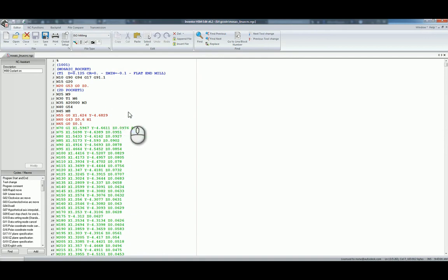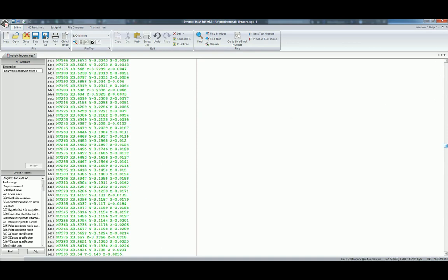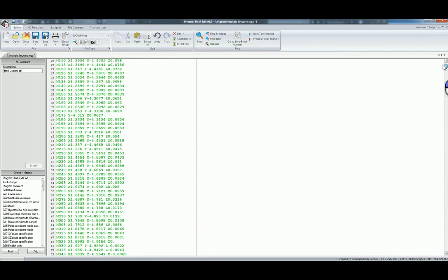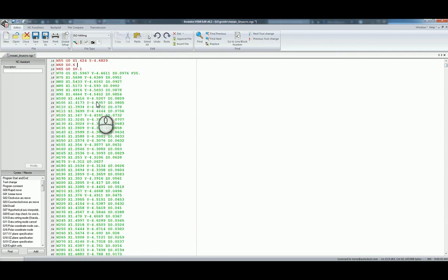However, I don't think we're running tool length compensation. I think we need to change this G43. In fact, we need to just take it out. This way the tool will go right to these coordinates based off what we set. Let's check the bottom of the program, everything looks reasonable here. So only that one change needed for the Larkin routers running Linux CNC.